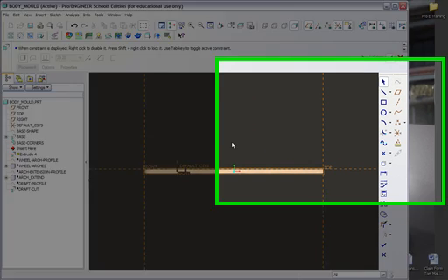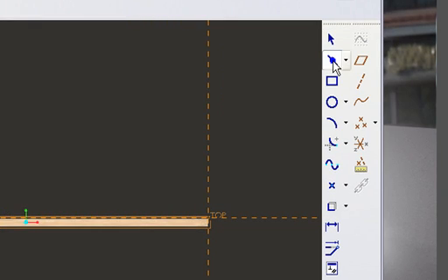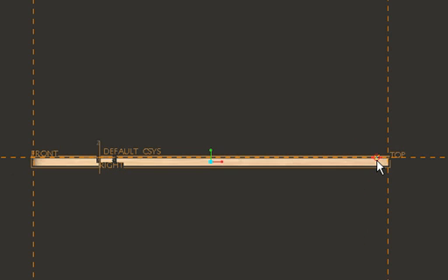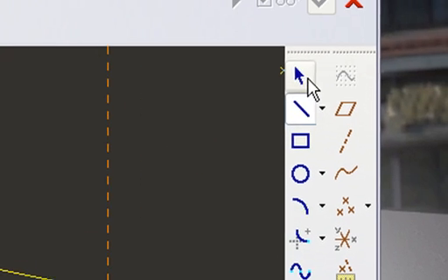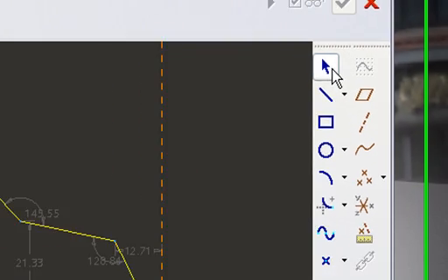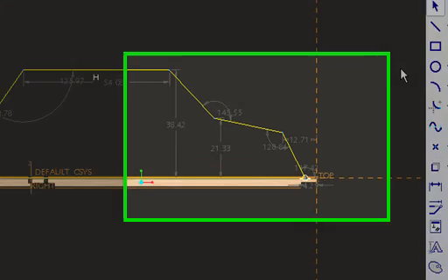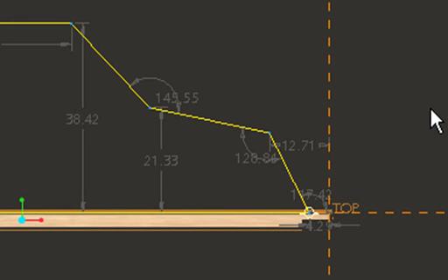Now let's create our sketch. Select the line tool from the tray and then click where I click. Make sure this one is horizontal. And now close the sketch by clicking here and then middle clicking to finish the line tool. You'll notice when we click the select tool from the tray that all the dimensions have loaded up into our model. What you'll also notice is that these dimensions are wrong, so we need to create our own.